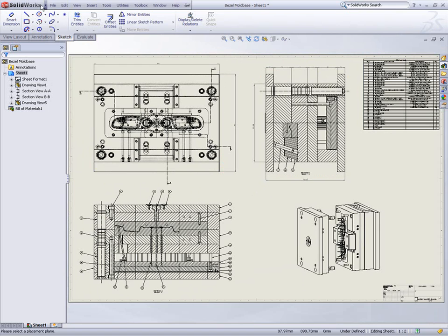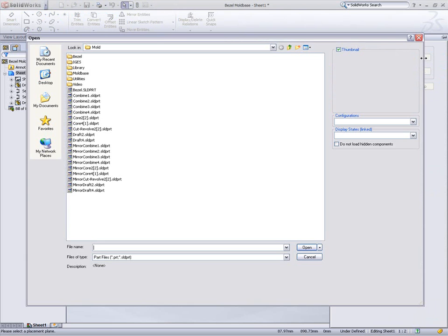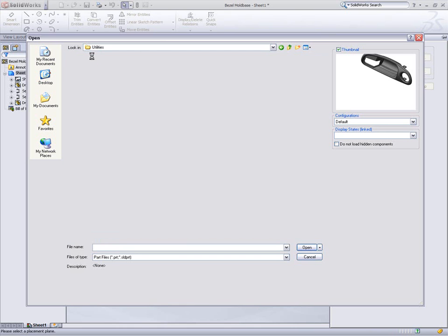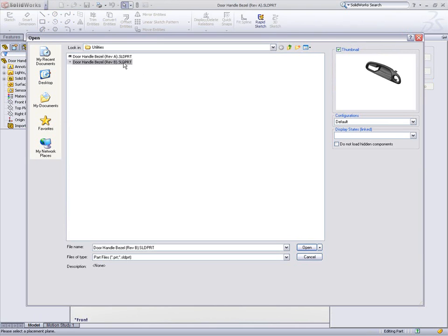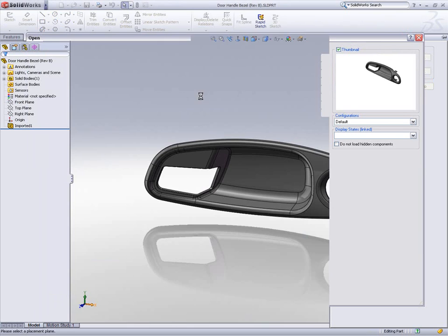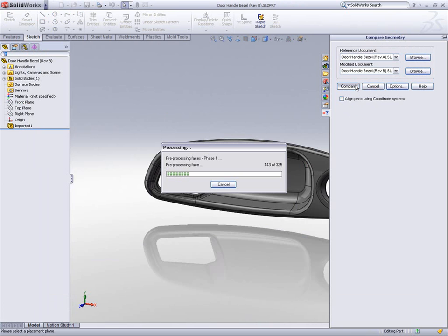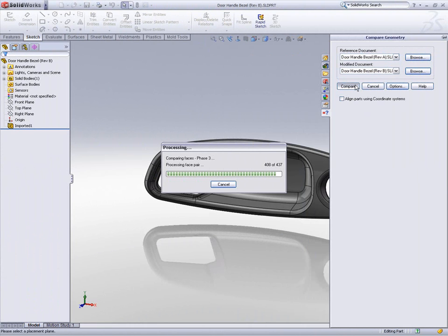In an ideal world, the customer would never change their mind. Unfortunately, they do. But fortunately, SolidWorks has a number of tools to alleviate rework caused by drastic changes to the design. SolidWorks Utilities can be used to compare geometry between parts and accurately detail the differences between the two. By choosing two revisions of a part, each face is compared and color-coded to give an easy-to-read graphical feedback. This can take a couple of minutes to complete, but the results are worth the wait.